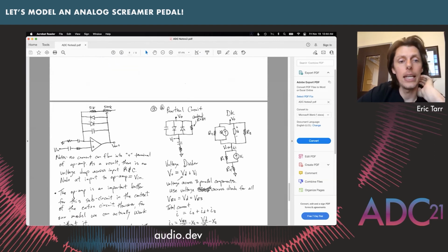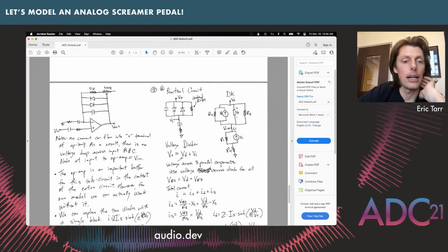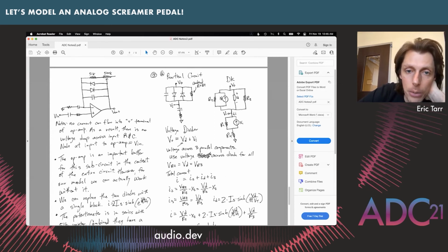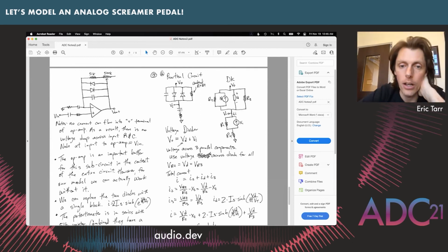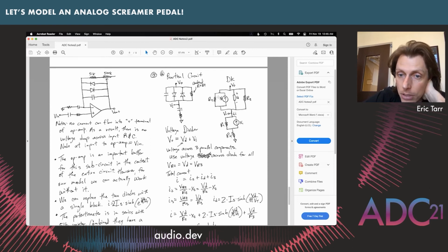So here's what it looks like inside of ElectroSmash. When we start to ignore these things here at the beginning, then we just have this happening, where we have Vout right here, going through these components to a VN node that's right here. And then we have VN going across this capacitor and across this resistor right here. So I've ignored these things as a way to simplify our lives. I'm also going to substitute in for this pair of diodes right here with VD. And then I'm going to substitute in for this capacitor with the decay method for both of these right there.